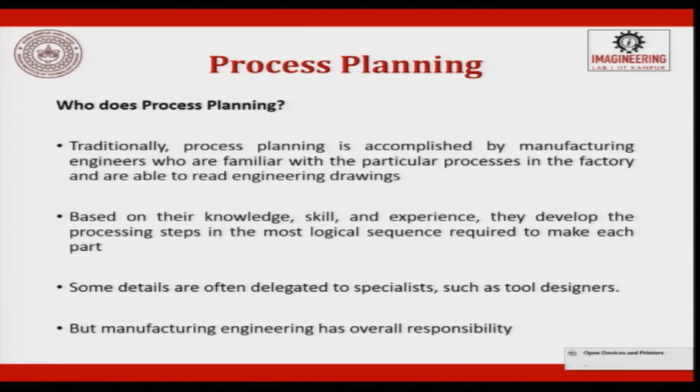Then in each process there will be fixtures, and when he talks about a fixture, he has to look at the datum, which datum has to be fixed, and then subsequent operations have to be done with respect to that datum, such that when we do assembly there will not be any problem. So, this is a highly skilled job. Now, we will see who does this process planning.